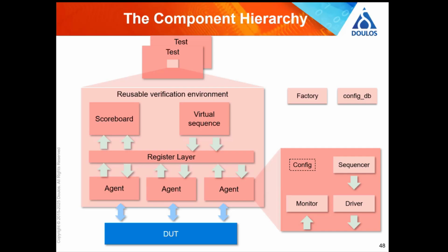So here's a block diagram, and you can already see it's more complicated. There's loads of stuff going on here. You can see in the bottom right-hand corner, we've got these keywords monitor and driver. Talked about those already. The driver is taking the transactions and converting them to the ones and zeros that the DUT understands, and the monitor's doing the opposite. UVM is more complicated, basically.